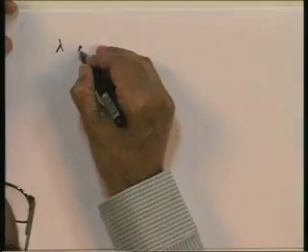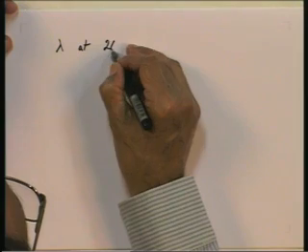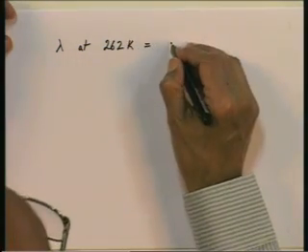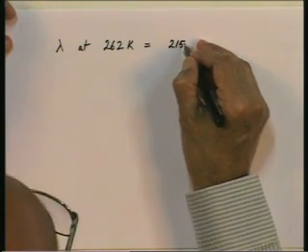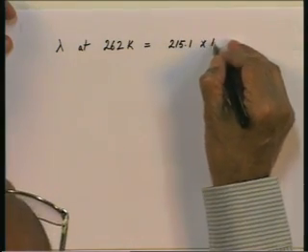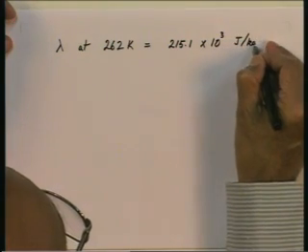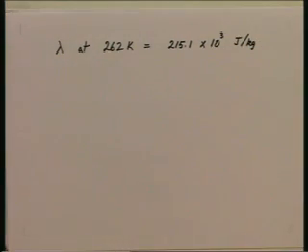In addition, we will need the latent heat, of course. So, let me put that down. From the tables, we need the latent heat, and that would be at the saturation temperature. So, latent heat would be at 262 K for R22 vapor. If you look it up in the tables for R22, it is 215.1 into 10 to the power of 3 joules per kilogram. So, these are the relevant properties that we need.